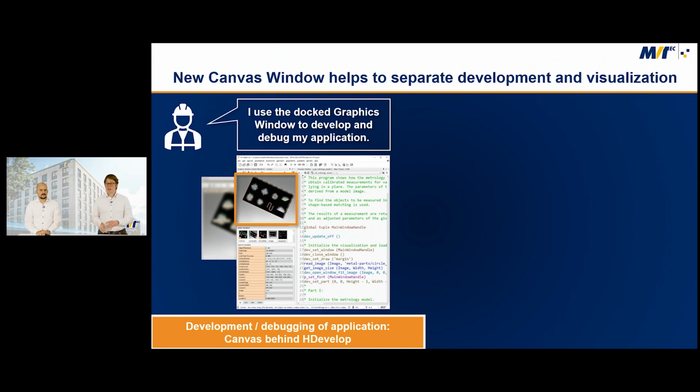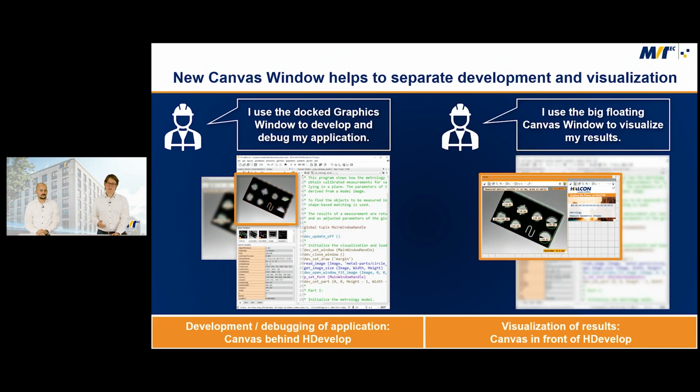We have changed the default settings from a docked canvas in your HDevelop to a single graphics window, which is now docked on the left side of your HDevelop, because we think that is enough to debug your code. You can visualize whatever is now relevant for you in your process, and the canvas will now be used to visualize your running script.